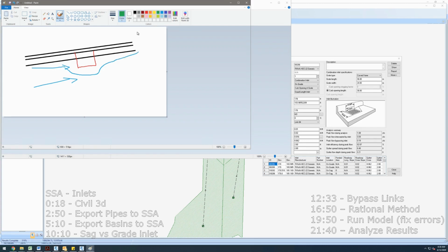On a flatter slope, water is not going to move as quickly, so it's going to kind of pond outside farther, and so you're going to have more water that's bypassing your inlet. A little bit counterintuitive, but that is how the calcs work.